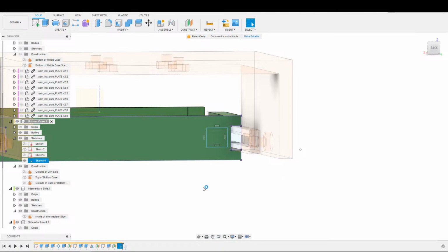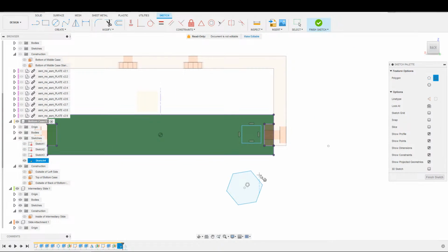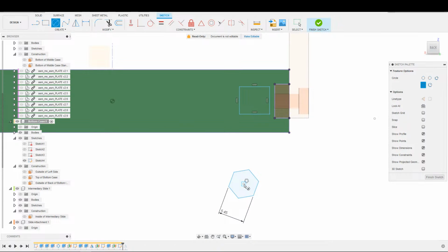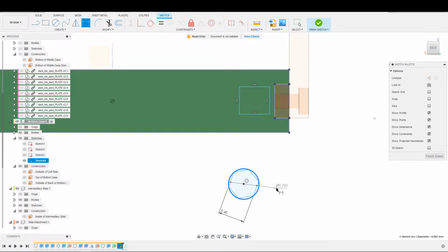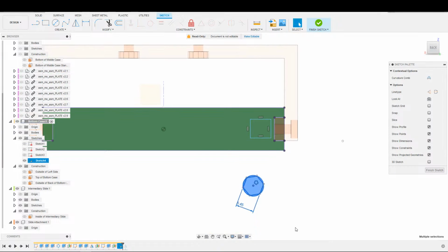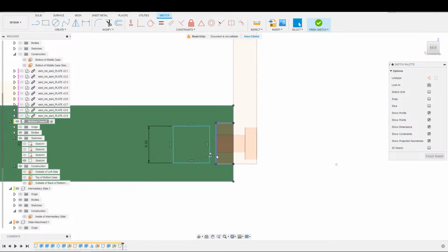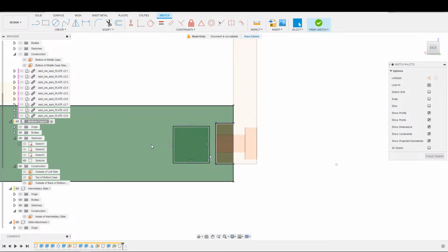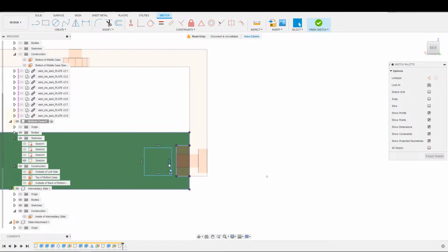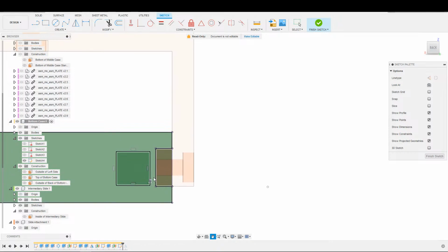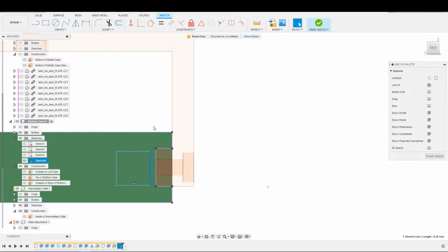Back to the maths. So here's my hex nut. This is 5.45, and this whole entire diameter therefore is 6.3. All right, good to know. So we need 6.3 on this edge, 6.3, which is actually less than the slide height. So I'm going to prefer that instead. And the bolt itself is like 2 millimeters. I'm going to give ourselves 4 millimeters just as a safety clearance. So that is how we are going to do this.